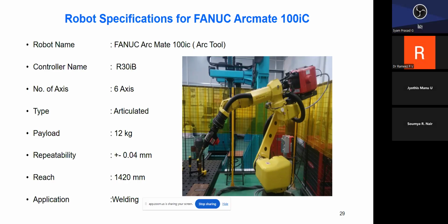In the Fronius power source, we have the beautiful technology called cold metal transfer technology. By using that, we are making 3D printing of components, right? So far we tried with several materials: all aluminum alloy grades, all stainless steel, super alloys, cobalt based alloys.